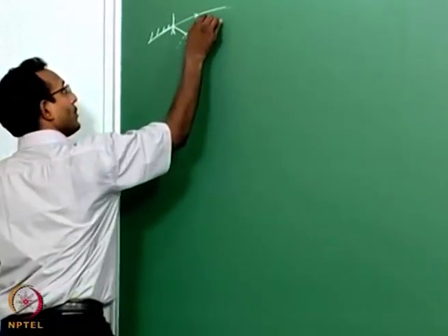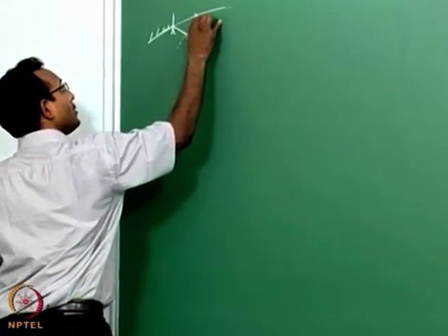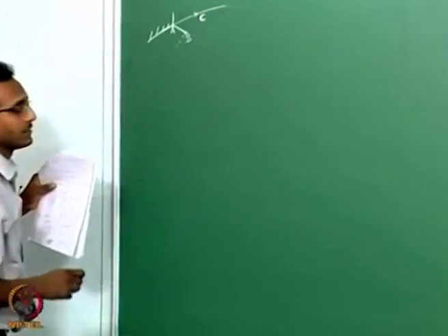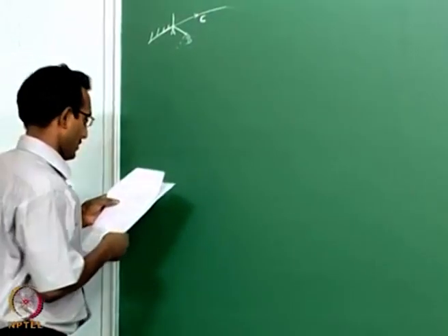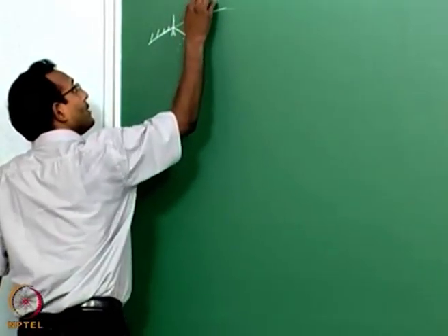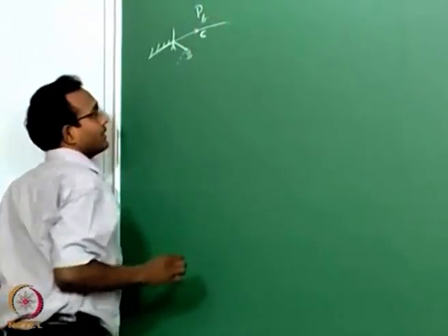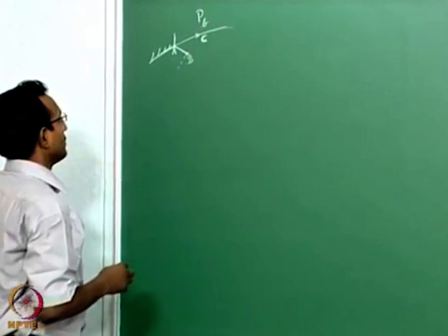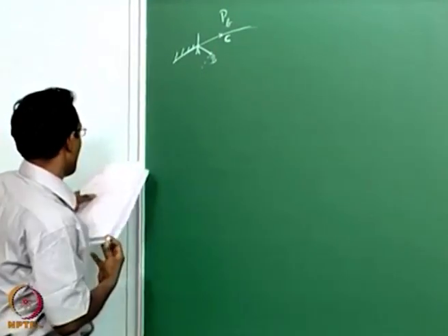I want to find a point C on the pressure boundary of this jet. Since it is a pressure boundary, I know my exit pressure, the back pressure there, that is given, and now I just have to go and find these points.